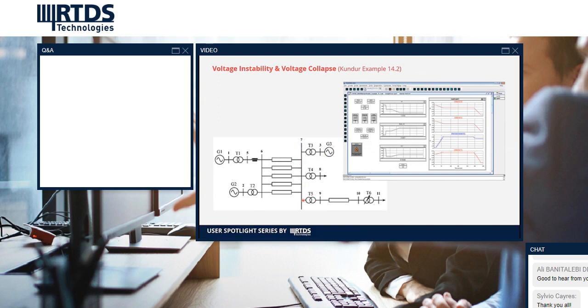This is a 500 kV bus, and then into your distribution network. The tap changer at this transformer starts to respond to try and bring the voltage at this bus up, and in doing so, it draws more reactive power from the local generator. This generator then goes into field current limit, and ultimately the voltages of the system collapse. This all takes about 5 minutes.